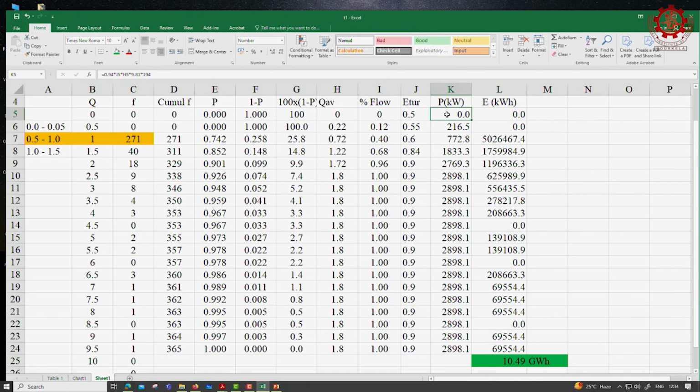If it is a Pelton turbine you can put equal turbines, 1500 into 2, assume this 2898 is 3000 and put 1500 into 2, and take the first machine to the maximum power, 1500, and then start the second machine, right. Here you have to restrict it to 1500, and then take the other machine from this point onward.